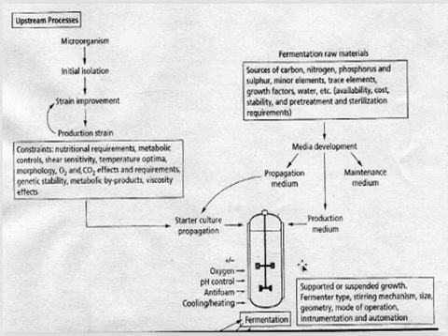You have to find out the optimum of these things, like what design will be most efficient, what kind of stirring mechanism will allow us to get maximum product, and what will be your aeration speed and mechanism. Also you have to put various controlling devices there to control the pH, the pressure, the foam, and the cooling and heating system. Basically you have to decide everything before you go for the final reactor.